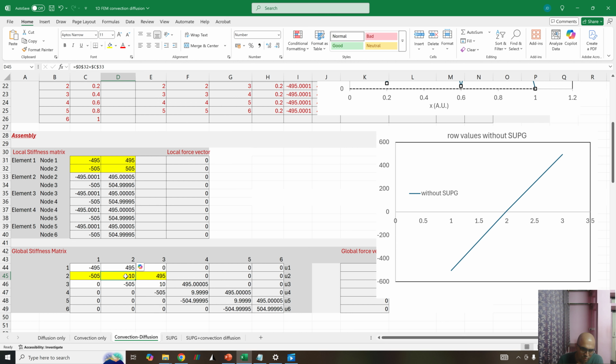This is the upstream term, this is the downstream term. The downstream term has a higher scaling and the upstream term has a lower scaling. If you do upwinding, the downstream guy will get pushed down and the upstream guy will get pushed up. So the diagonal term will again get dominance.